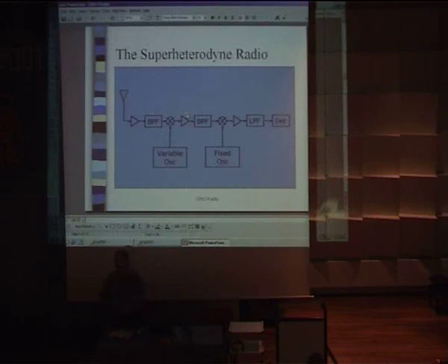An FM receiver is typically 10.7 megahertz. In various communication receivers it has different values; for microwave and radar stuff, it's either 70 megahertz or 140 megahertz. It varies, but you pick a fixed piece in here. So the frequency in this area would always be, for an FM receiver, 10.7 megahertz. By varying this here, I get to select whichever difference it is, and I can steer that through.